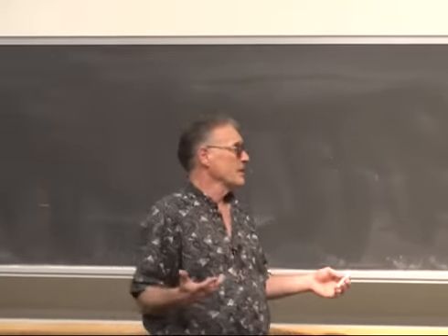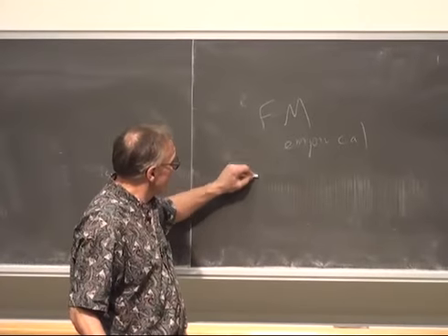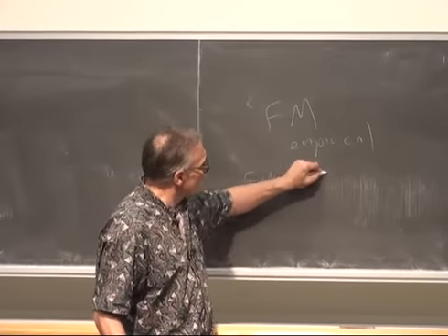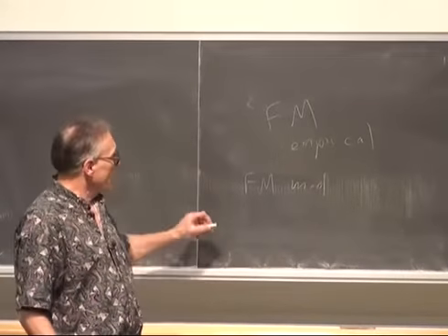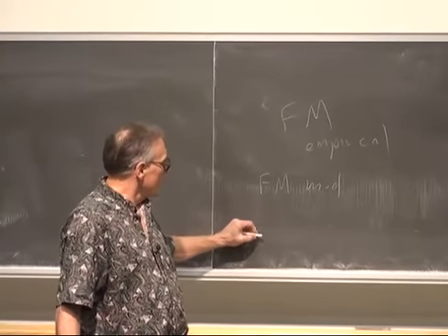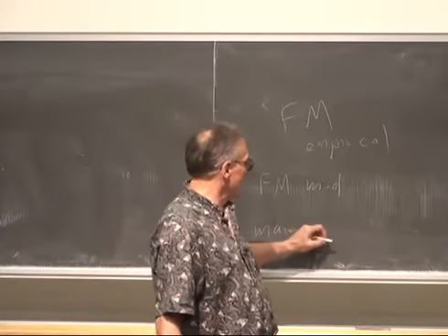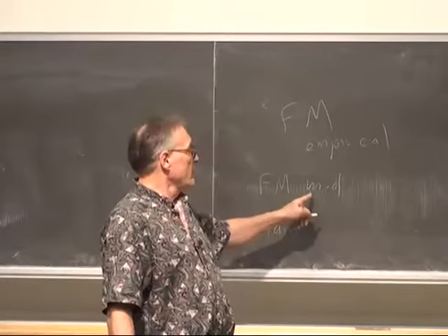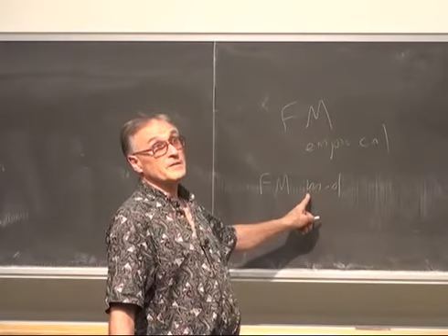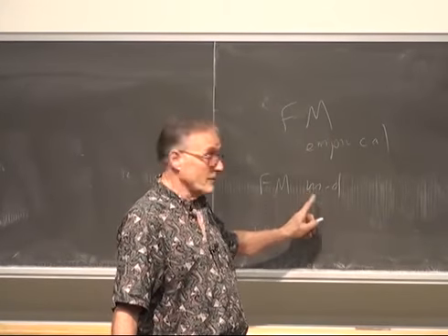The idea here is that you're going to pick some modulating frequency, some FM modulation frequency, and then your main frequency, your main output, is going to be given by the phase of the FM modulation plus the phase increment of the main frequency.